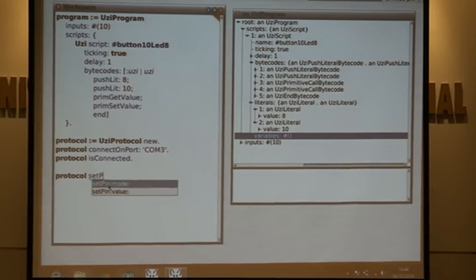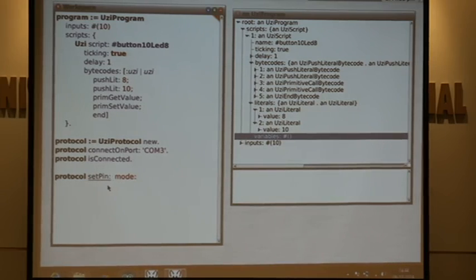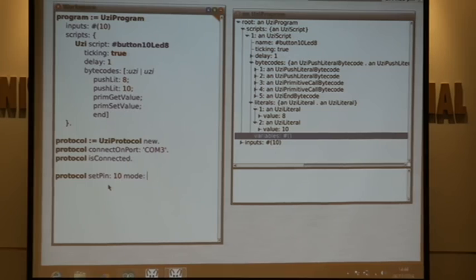Right. It doesn't work because I didn't set it as input. But I can say, okay, set pin mode 10 as input, and now if I ask the value, it should work. I didn't press it, so I'm not pressing it, so it's 1. Okay. So with this, this kind of works like the direct mode I used to have, right?